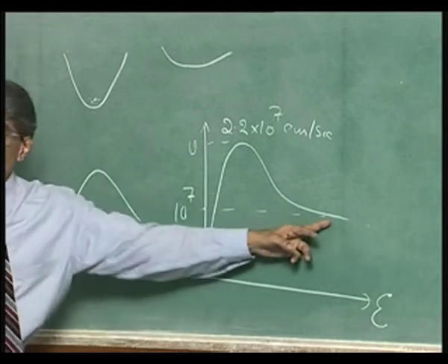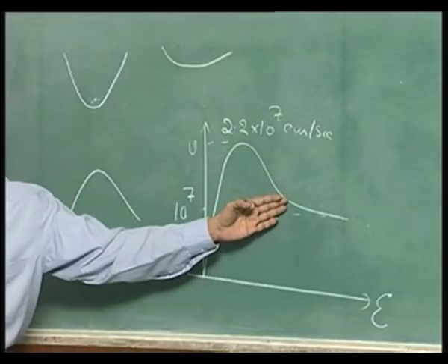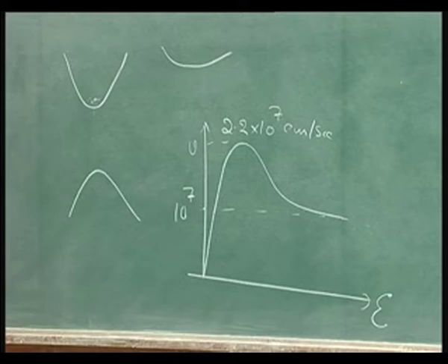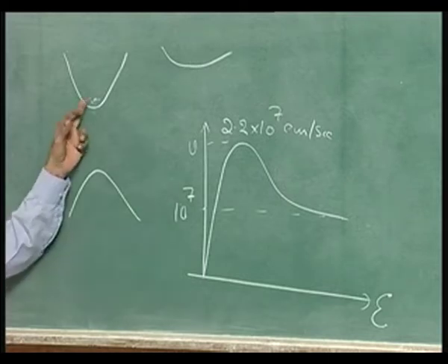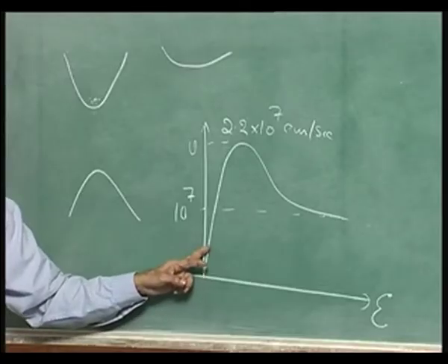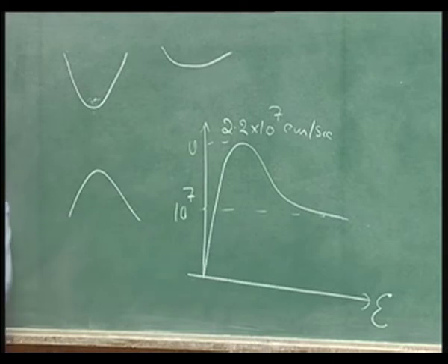Now, suppose I subject it to this high field right away. For example, if I put 10 kV per centimeter, you are down here, what would happen? The electron which is present here is immediately subjected to that high field and it experiences the benefits of being here. What I imply is it experiences a smaller effective mass. So, it has high mobility, but now the field that it experiences is very high. If I am here, it is a different issue, the field is low. But if I apply high field suddenly, launching the electron into a region where high fields are present, then it will get accelerated to very high velocities.